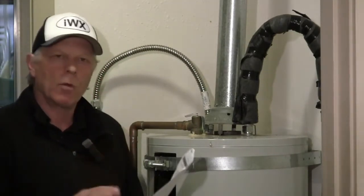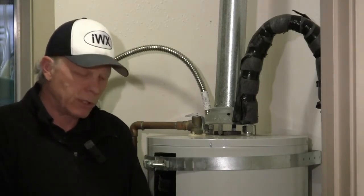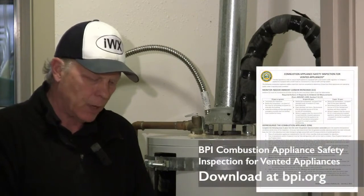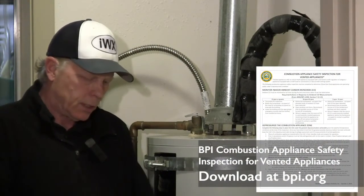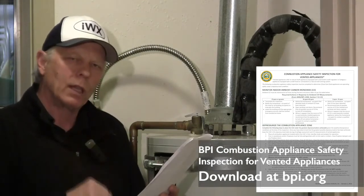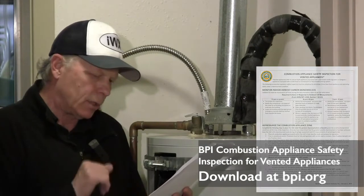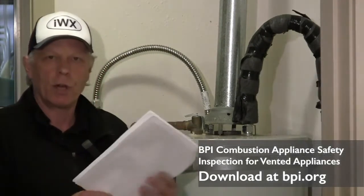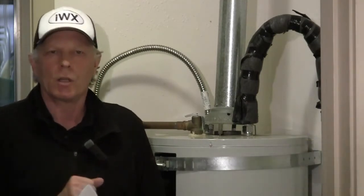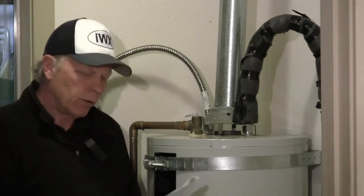There's two things you need to be familiar with in the standard here, and one of them is the CO thresholds table. It's called Table 1 in the BPI document. Table 1, CO thresholds, will let you know what level of CO is acceptable. And for water heaters on this table, it's 200 parts per million air free. And we only had 27 parts per million air free in here. So we didn't reach the threshold.